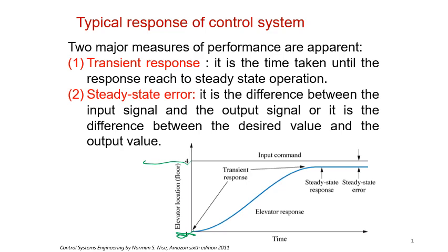By pressing on the lift, I am assuming that I am going to level 4. That's a step signal. So the lift will start operating, going up, up, up, up until we reach level 4. Is the lift going to go to level 4 exactly? Or will there be even a few millimeters of difference? That's going to be considered as an error.